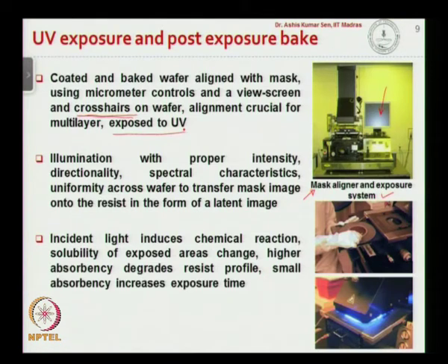So, immediately after exposure, if you have a mask pattern and you do a UV exposure through the mask onto a resist-coated wafer, after the UV exposure you can actually see the latent image getting transferred to the surface. The entire process is a photochemical reaction that gets initiated when you expose the UV light onto the resist.